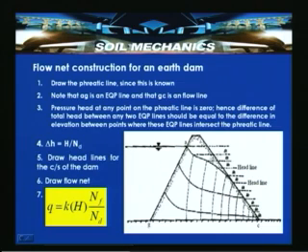So, the first procedure is drawing the embankment to scale, then constructing and establishing the phreatic surface by adopting the procedures discussed in the previous slides. Then draw the equipotential lines for the cross section of the dam with the delta H. Simply divide into the number of equipotential drops, and from there draw the flow net. Again, seeing that this is a flow line, maintain orthogonality and see that these curvilinear squares are maintained.